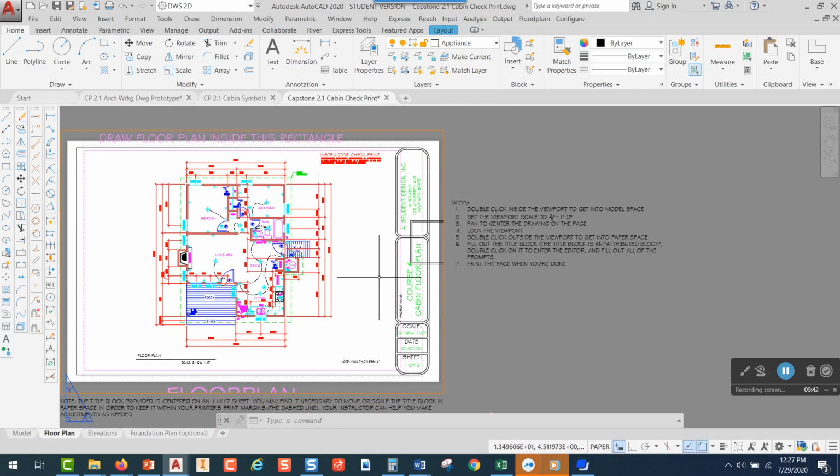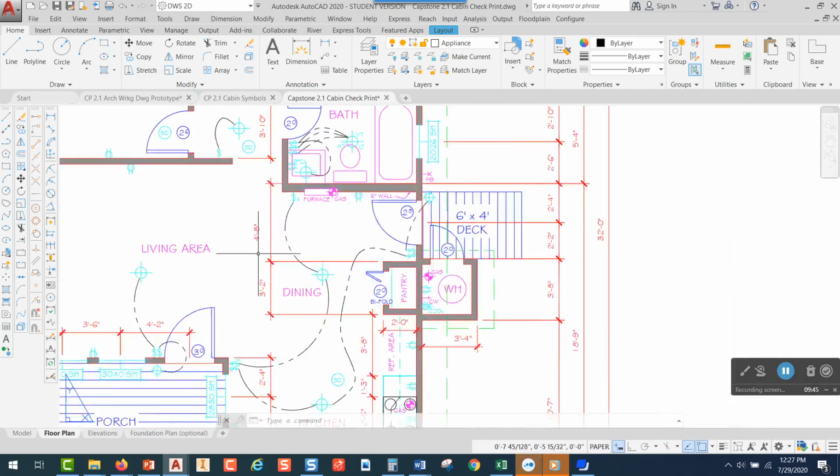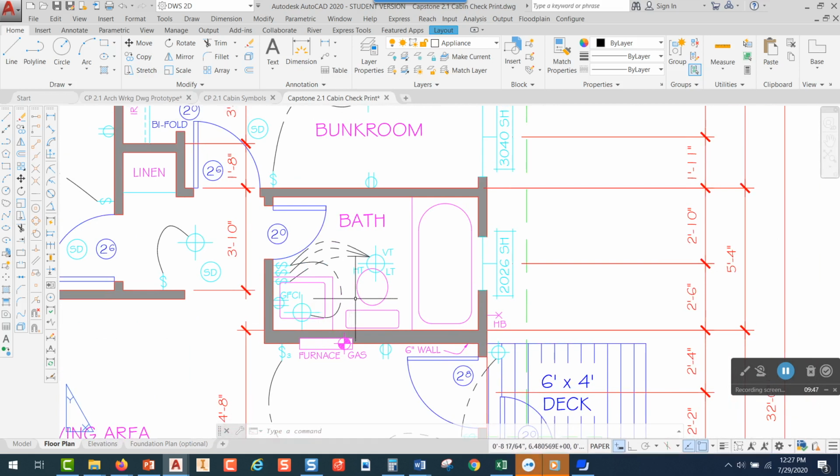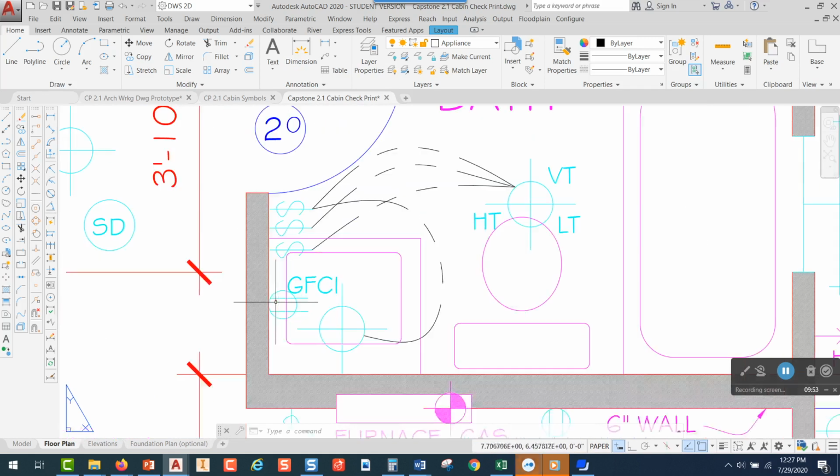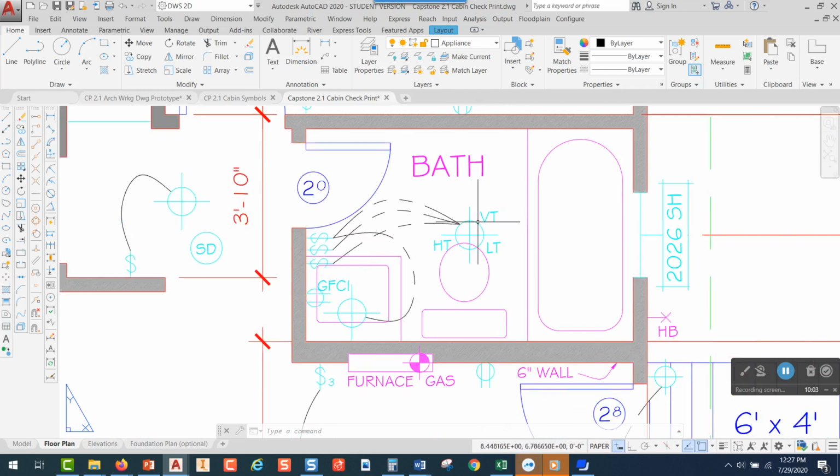All right. I wanted to show you some of the symbols that are in this floor plan. So we have a tub, and we have a toilet, and we have a little sink area. We have a 120 volt outlet that says GFCI. That's a ground fault circuit interrupt outlet that's required next to a sink like this. Here's that light I was telling you about that says vent, heater, and light, and there are 3 switches on this wall, and for each switch, we have a phantom line going to our light right here. These are the switch lines for that.